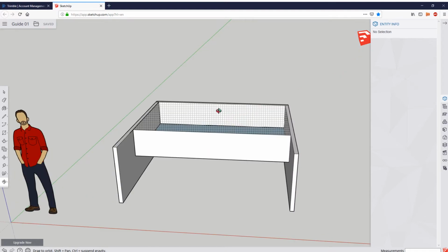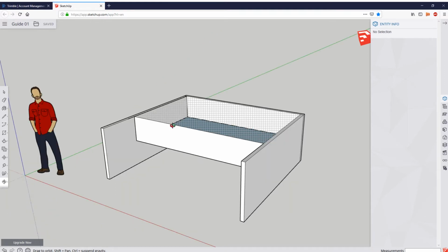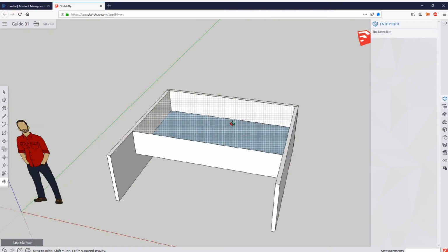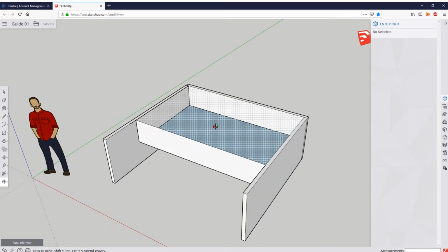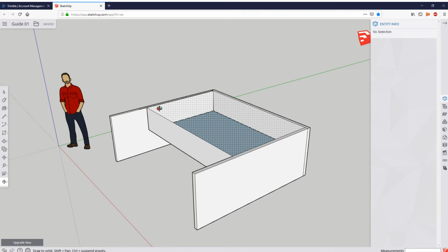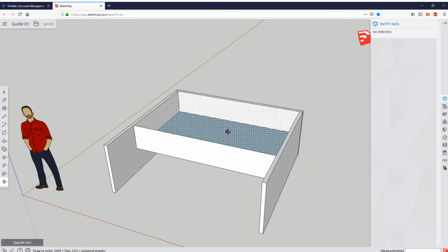You could easily have it with less, but that really depends on if you want the compartment to be bigger or smaller. Bigger obviously gives you more freedom, gives you more air in the enclosure, so airflow is less of an issue. Even if the airflow is deficient for whatever reason, the fact that there's more air available in a bigger enclosure means that it will take longer to warm up, and the fans don't have to constantly be at full speed, as long as the air does get removed eventually.